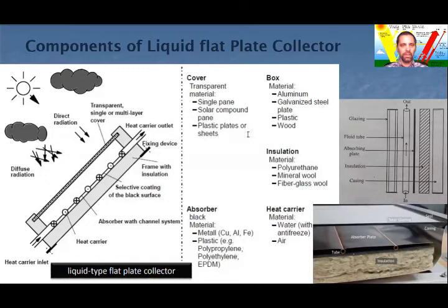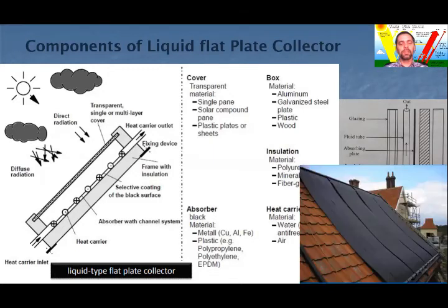If the back of the plate is protected by a heat-insulating material, and the exposed surface of the plate is painted black and is covered by one or two glass sheets, then the equilibrium temperature will be much higher than that for a simple exposed sheet. The water circulating system, either by making it hollow or by attaching metal pipes to the surface, transfers the heated liquid to a storage tank.